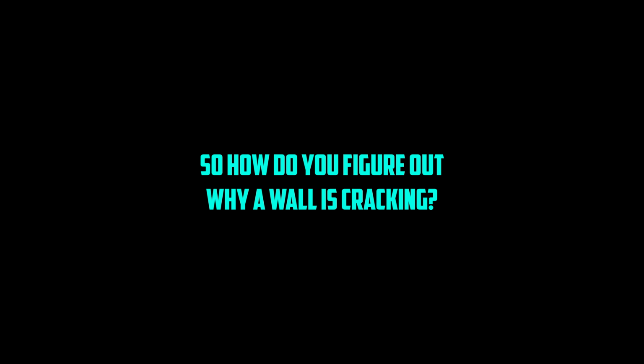It's often the main symptom, and it's not just cosmetic. Bad cracks affect stability, let rain and drafts in, waste heat, reduce sound insulation, and obviously hit the property value. So how do you figure out why a wall is cracking?